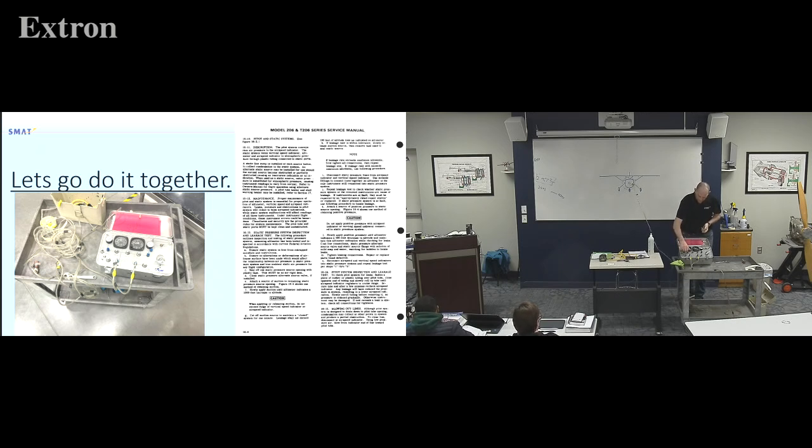So, if I were to do that again, bring it up, normally you don't want to just pull it off. There's a vent, so when you disconnect things, you can just open this up and you can slowly vent the pressure. There it goes. Very fine-tuned valves, and you can vent that down. So, we'll say this is hooked up to an airplane. We just checked our pitot system. It doesn't leak. Everybody good with that?